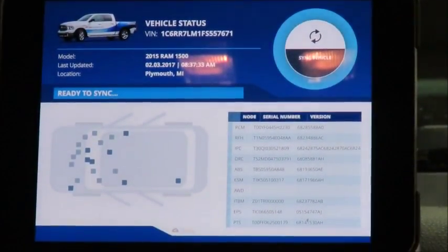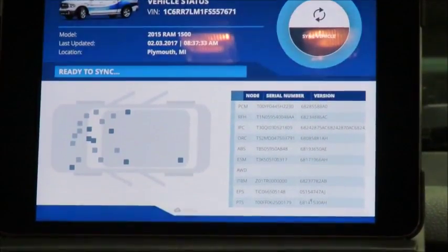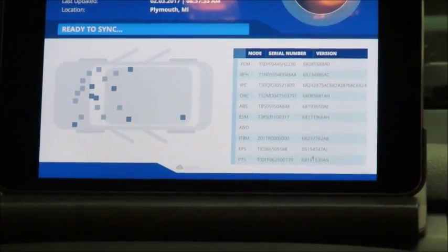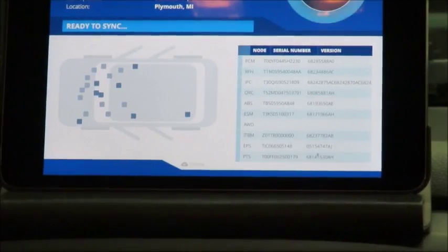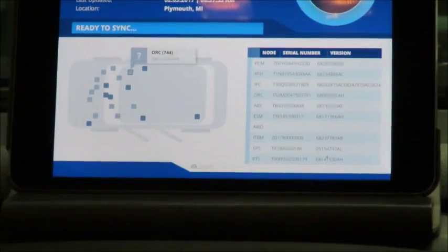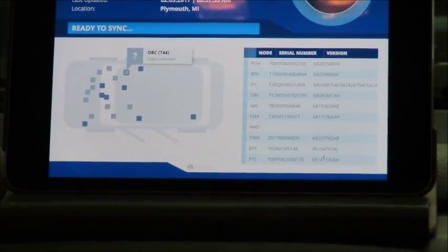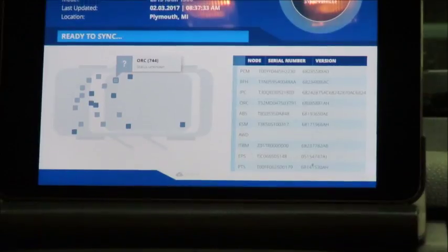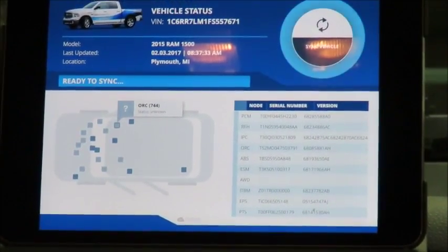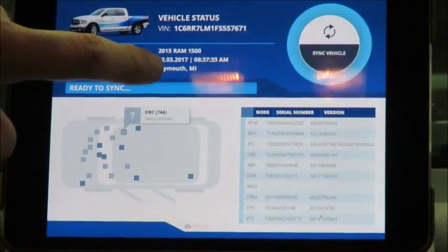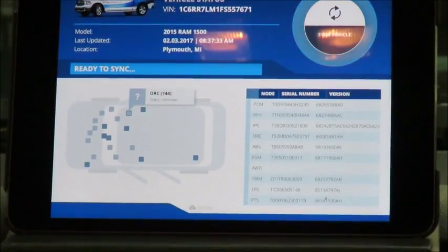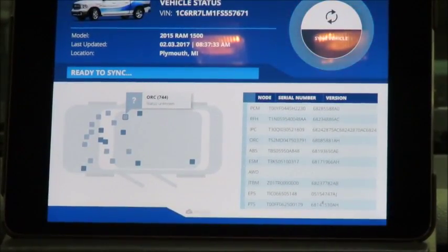In the lower right-hand corner, you will see a list of all the ECU modules that are located in the vehicle. The list contains the various hardware and software part numbers installed. The graphical display on the left shows a rough location of where the modules exist within the vehicle. After each update, we can also receive additional diagnostic data, including potentially the vehicle's location, shown in the information below the vehicle. This could be used by the back-end OTA cloud for geofence distribution of updates.